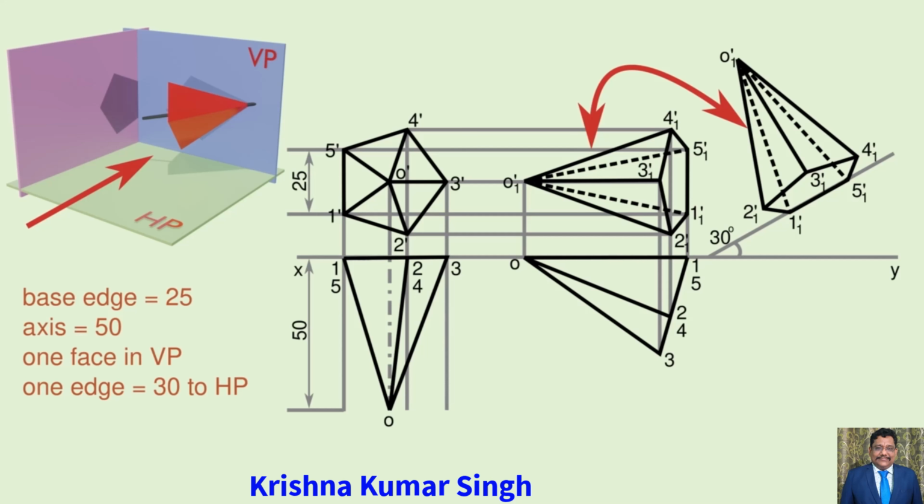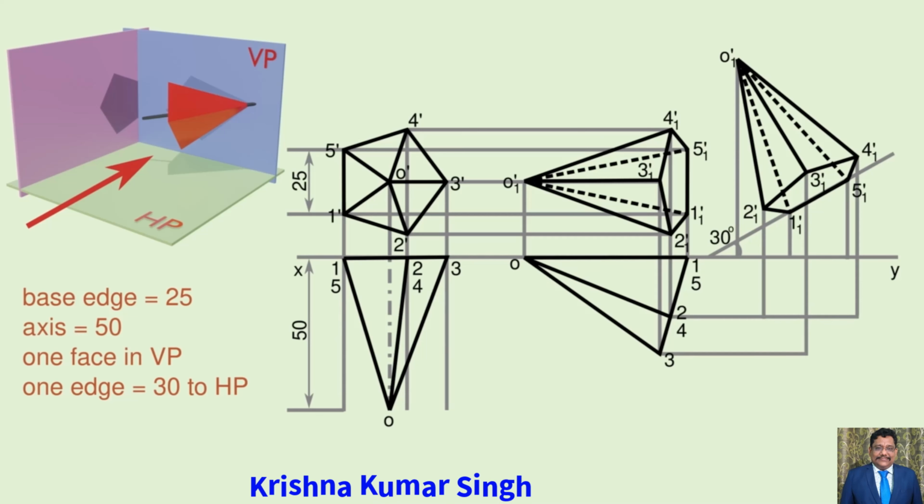So tilt the front view. Give numbering to the corners. This is the required front view. Now we have to project the final top view of the problem. For that, draw the construction lines downwards from the step 3 front view and towards the right from the step 2 top view. Now we can see that all construction lines will intersect each other at some points.